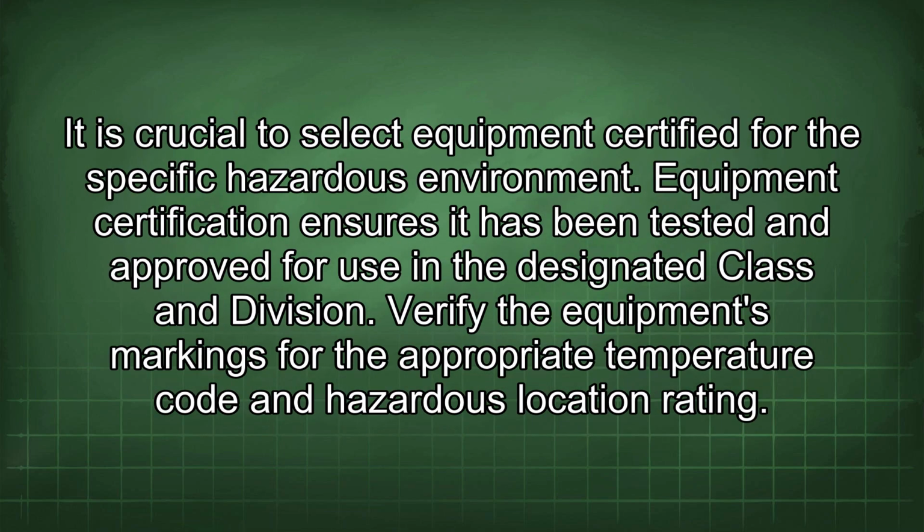It is crucial to select equipment certified for the specific hazardous environment. Equipment certification ensures it has been tested and approved for use in the designated class and division. Verify the equipment's markings for the appropriate temperature code and hazardous location rating.